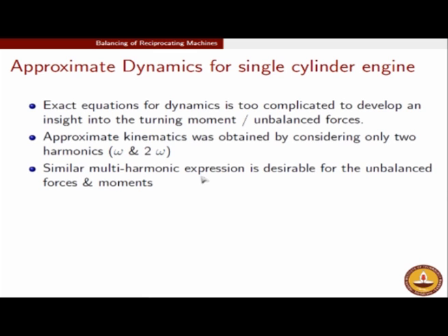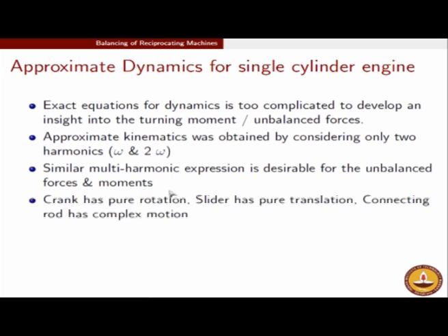We want a similar multi-harmonic expression, and that is very desirable for the unbalanced forces and moments, because most of the time in vibration the frequency of vibration is very important from the design perspective. So if you know the harmonics and the amplitudes associated with them, it will be of great help in designing appropriate mounts, for example.